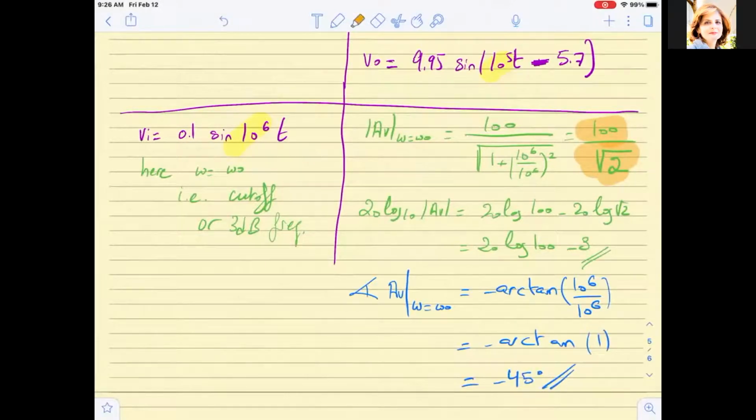So this is another property of operating at the, if I have a single pole, and I am operating at that specific single pole, the phase is going to be equal to 45. So if my system is represented by one expression that has a dominant cutoff frequency, I have one cutoff frequency, okay? And we will explain this in more detail. The phase at the 3 dB frequency is going to be minus 45 degrees.